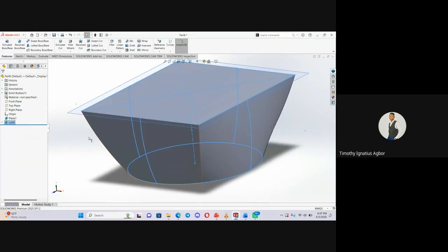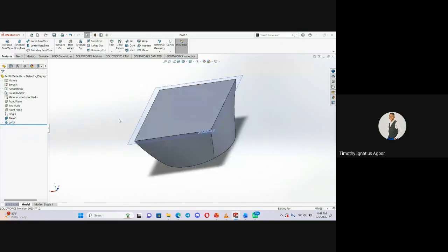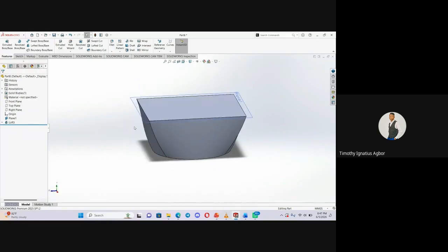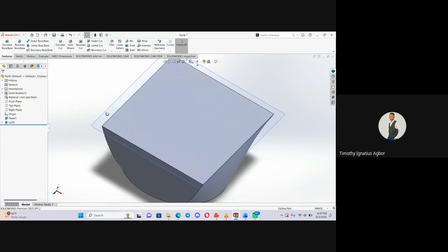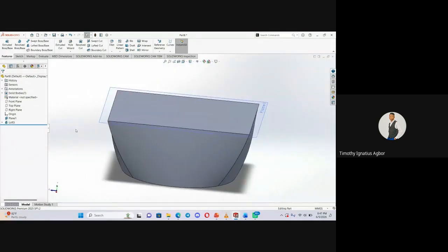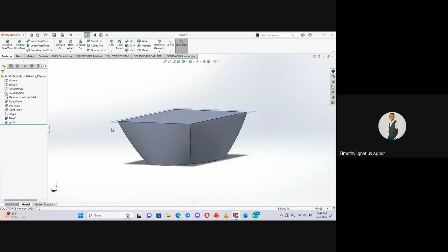So you see it is now working. It's looking like what we want. So always note to always merge and to pierce and coincide your sketches with your profile. If not, you'll be having that error that we just troubleshot. So that's how to apply guide curve.